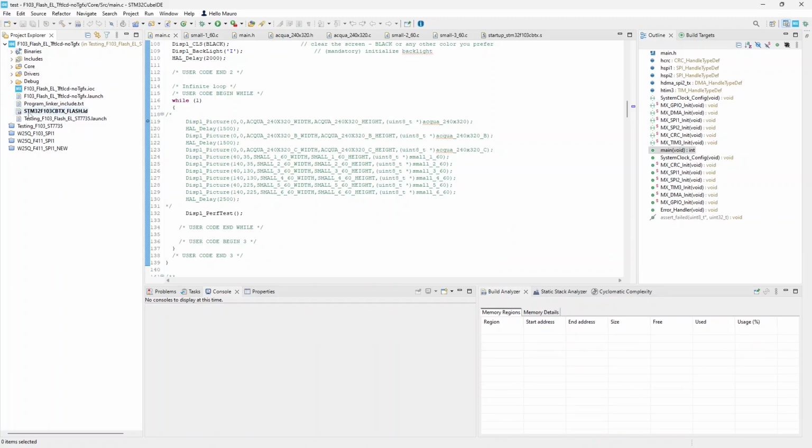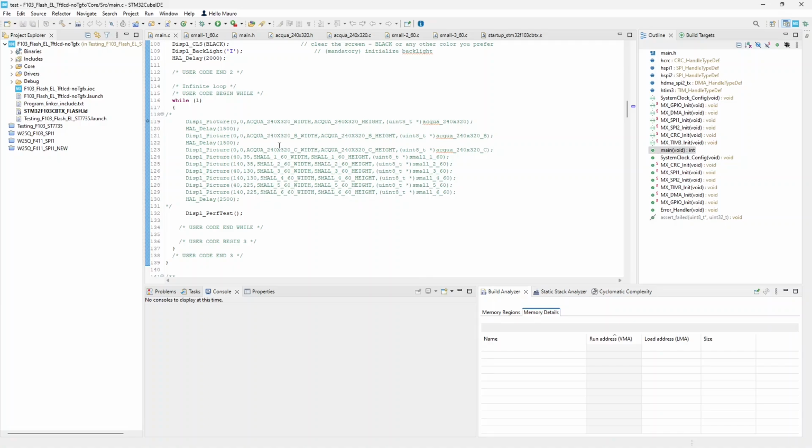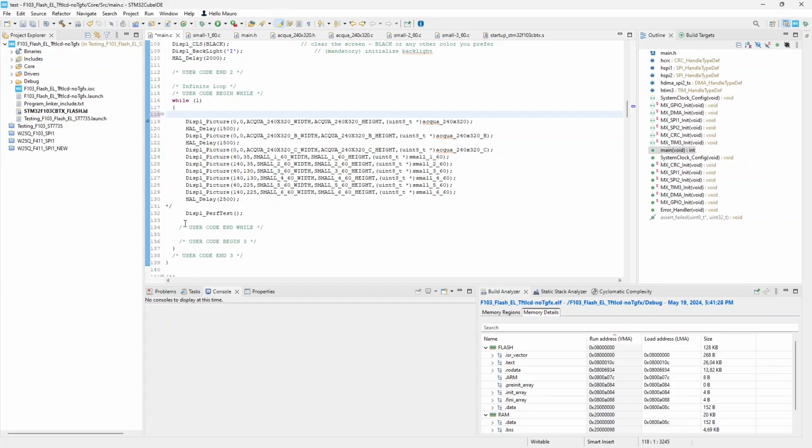Okay, we have seen that configuring the linker script mapping the external flash on the microcontroller memory address space, and with the help of an external loader we previously made for our project, we can really easily handle SPI Flash, storing data and programming it together with the microcontroller internal flash. But what about retrieving data? Is there a similar easy way to transparently handle data read from flash, regardless if it is stored on the internal or on the external memory?